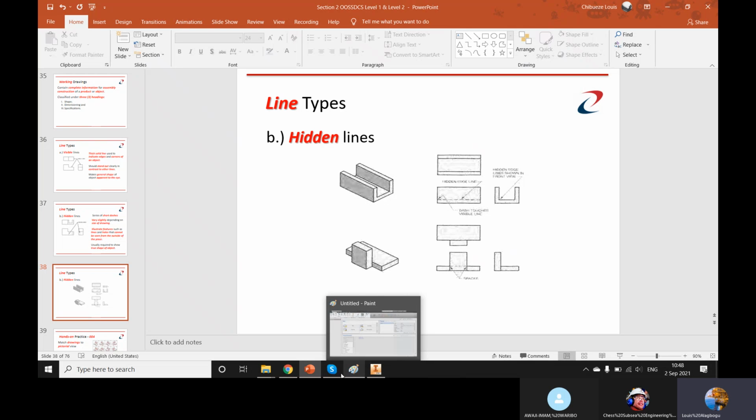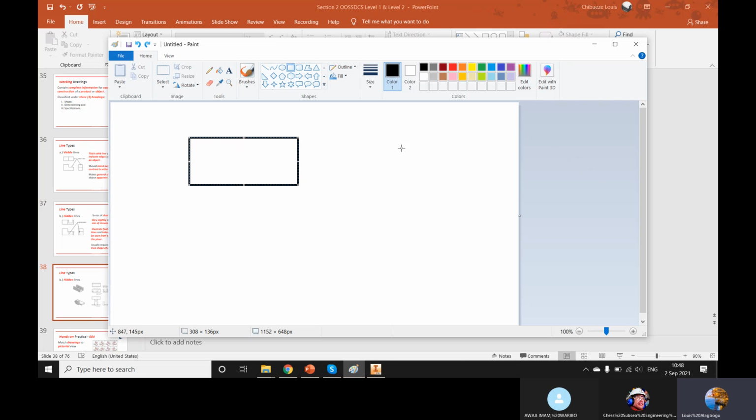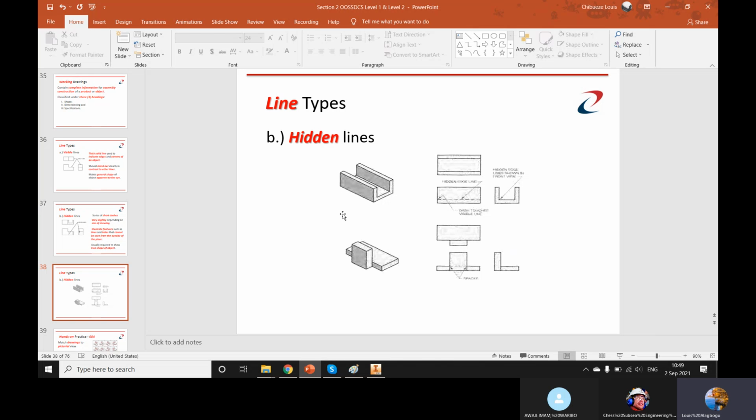because it's proper to go further to show the hidden line here, showing that there's a part of the image that was cut. This should be a dotted line. It should not be a continuous line. So if you draw just that face, the person looking at the drawing may not truly understand it.